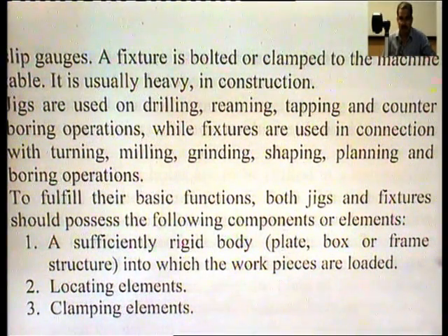Jigs are used on drilling, reaming, tapping and counterboring operations, while fixtures are used in connection with turning, milling, grinding, shaping, planing and boring operations. So, for light operations you can say jigs are used, and for heavy operations fixtures are used.